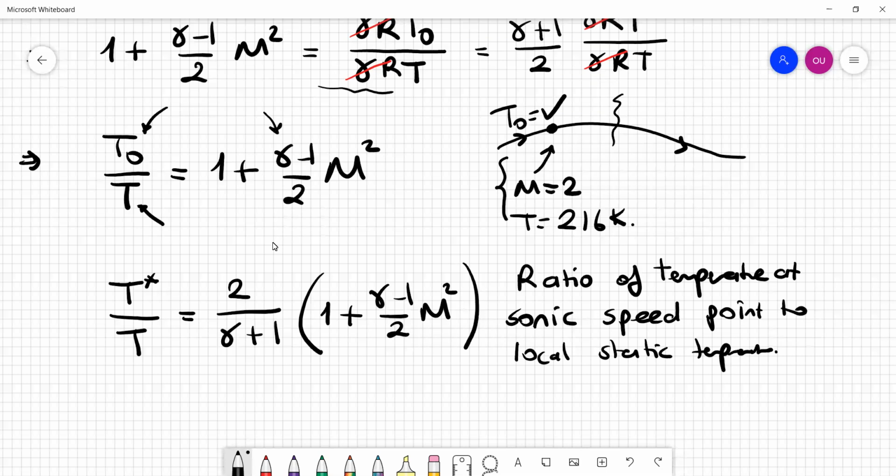Going back to the sketch here, this Mach number, with this given temperature, will correspond to some velocity. You can calculate the speed of sound from temperature, and then use the Mach number to calculate a velocity value. This velocity is obviously not the sonic condition, because Mach number is not equal to 1 here.